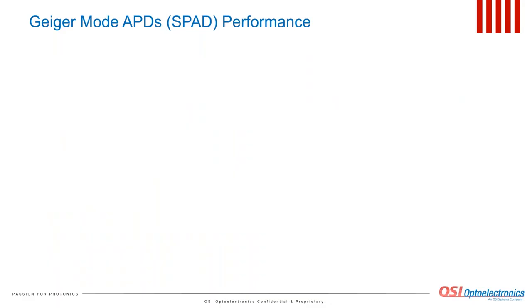Geiger mode APDs can only function if an effective avalanche quenching is provided. The simplest way to quench the avalanche is to add a quenching resistor in series with the APD. In this case, after starting the avalanche, the resistance of the diode drops dramatically, and the current flow through the quenching resistor causes a voltage drop on the resistor, decreasing thereby the bias across the APD. This stops the avalanche.